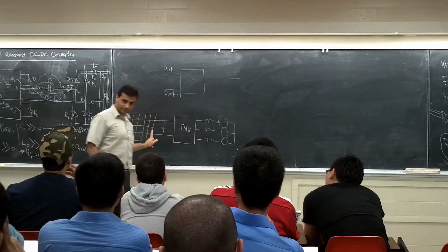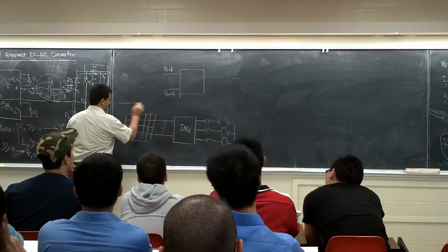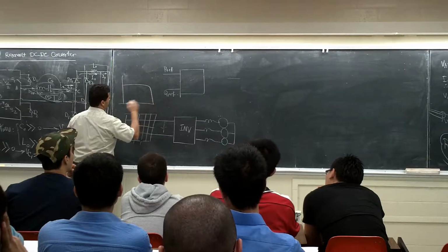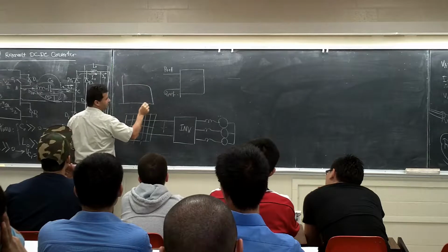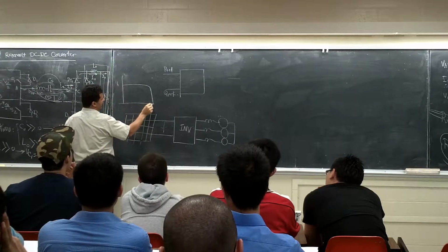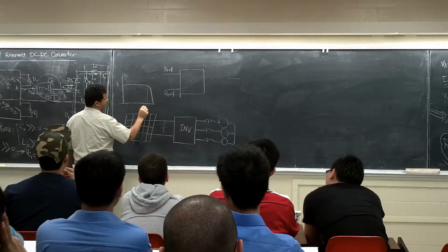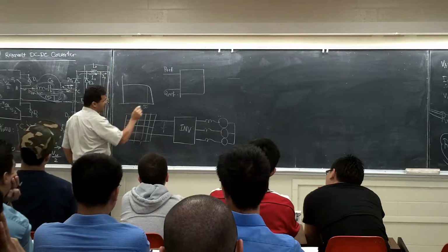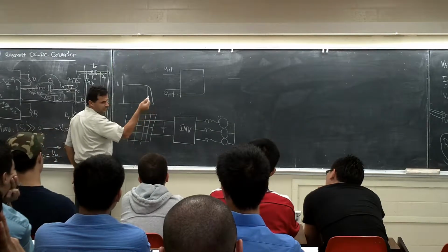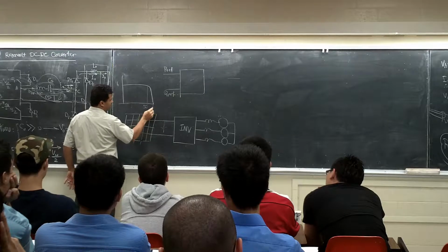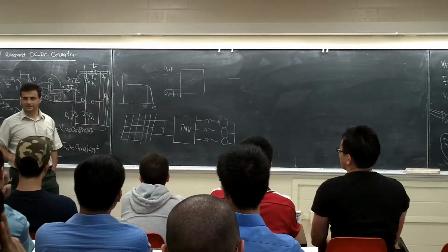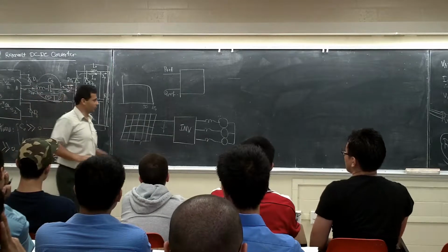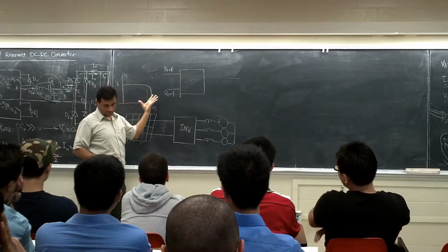Now here, I think the panel we gave you, I'm not sure how much it is, 6 amps, something like that. 6 amps? It is 6 amps. And I think here, I checked this for you, about 50 volt here. I think here is about 60 something, 65. We said, how many panels in series? 8. So basically, you can go to the PCM.